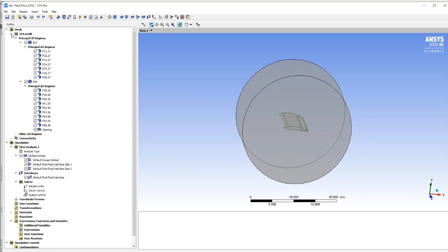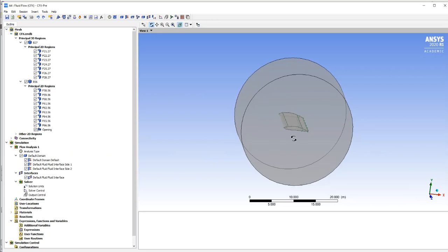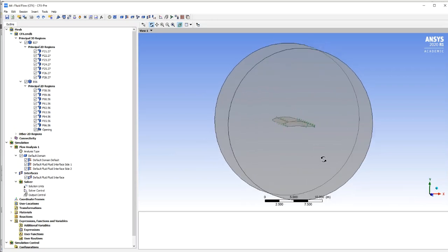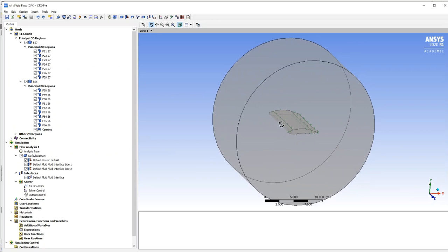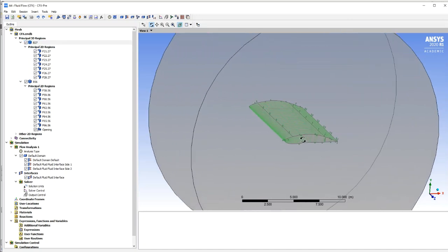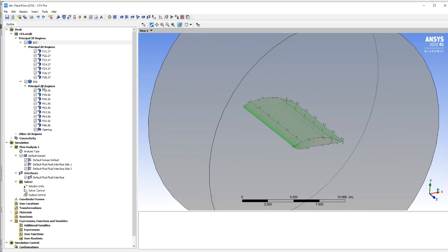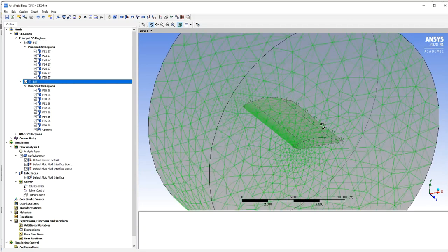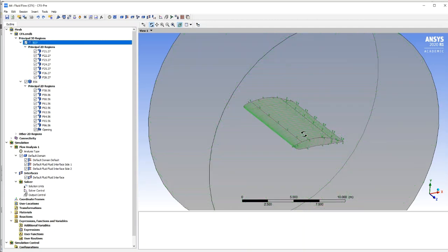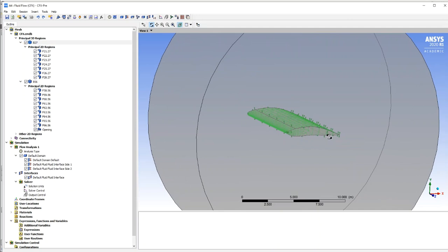So you can probably do also heat transfer calculations or calculations of the fuel inside the wing or any other calculations. So you also have a mesh for the wing. You have two meshes. You have a wet mesh for the wing and you have a mesh for the surrounding air. And maybe you need this to calculate any stresses inside the airfoil or any forces inside the airfoil and